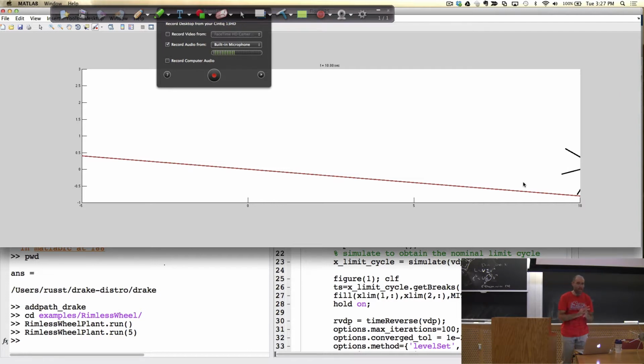So how can that possibly be stable? There are two things going on here with the energy of the system. It's gaining some energy by going down the ramp, and it's losing some energy every time it hits its foot on the ground. For it to be stable, those things are exactly balancing. That seems to be a critical point: it's a function of the angle of the slope. We're going to see exactly how it changes, but I can tell you that if I change the slope, it's going to change the walking speed, but it's going to be pretty robust to that.